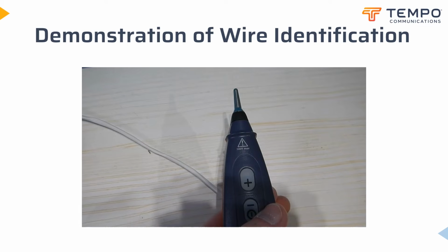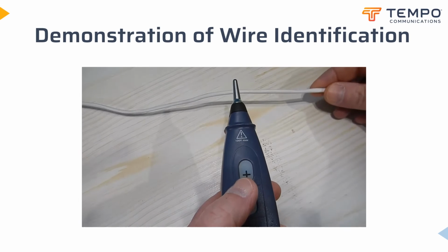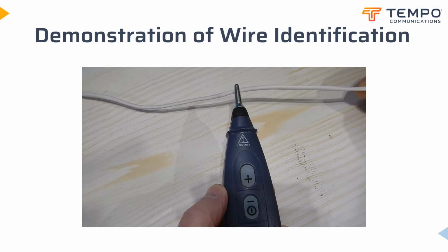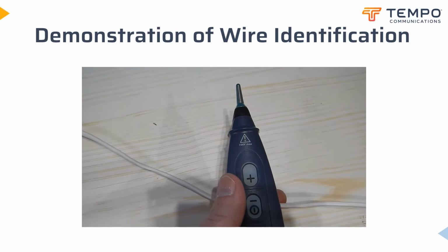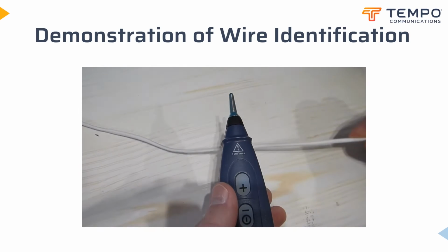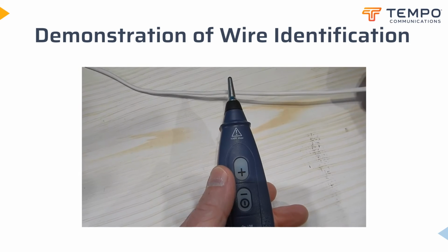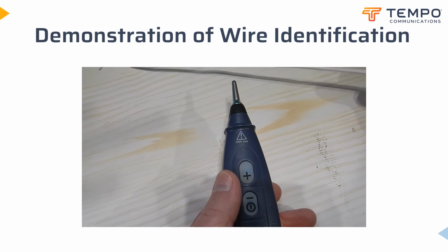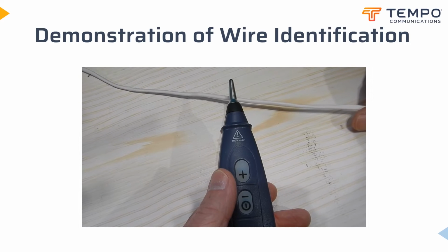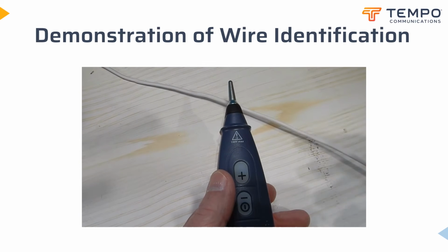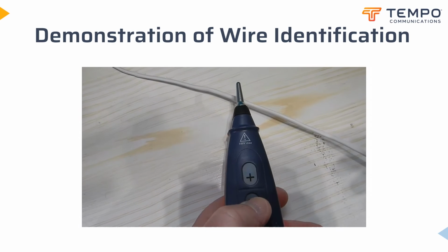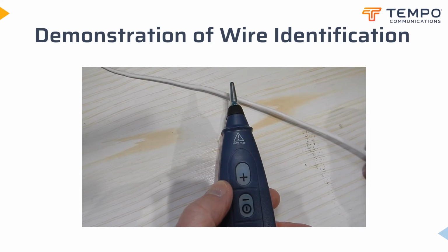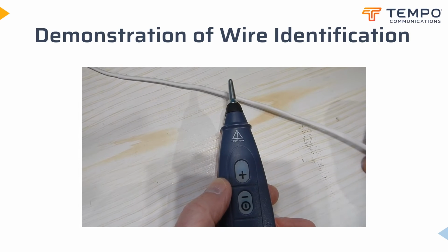Let's give you a simple practical demonstration in this attached video. This shows how electrostatic pair tracing can be done. Okay, here we have a simple household 3-pair telephone cable. I've applied a tone to one of the 3 pairs, and let's see how pair tracing actually works in real life. So if I first of all turn on the probe, you can hopefully hear that there's something beeping away in the background, so there's something going on.